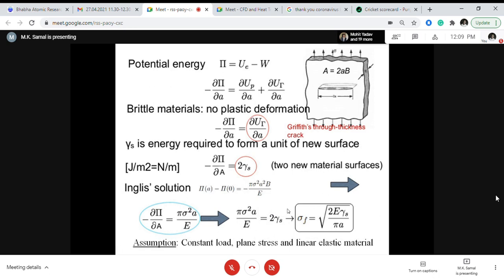But still, when the ductility loss is not large, the material also deforms plastically. For example, near the crack tip the stresses will be high, so the equivalent stress required for plastic yielding will exceed the yield stress. So near the crack tip there will be some plastic deformation, as in a ductile material.